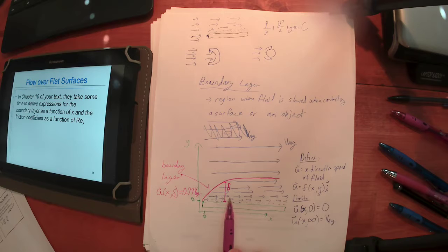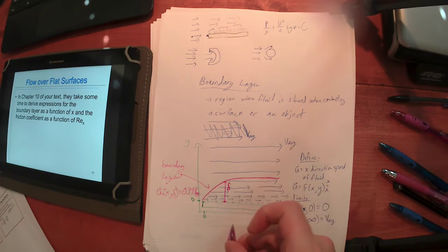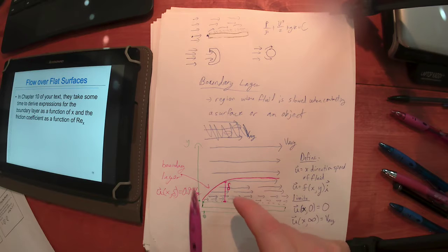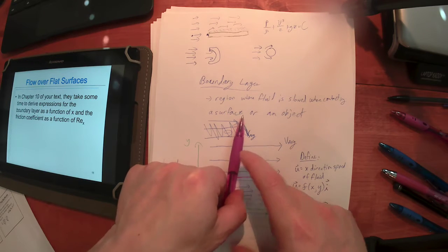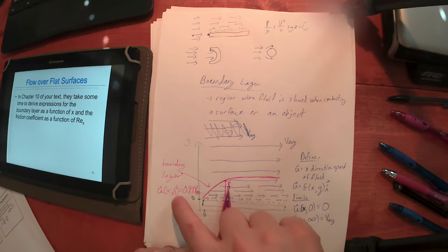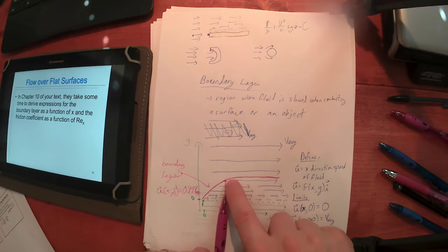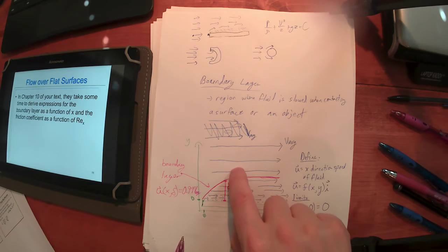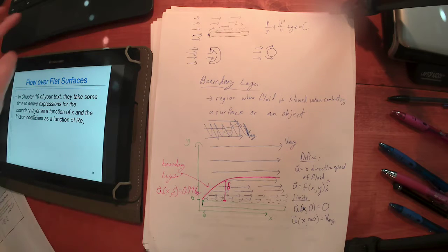And then they can move in a little bit further and measure the velocity there, and move in a little further and measure the velocity there. By measuring the length of the pin back here, they knew how far in they were, their Y value, and they could tell when they started detecting the boundary layer, when they kept getting the same speed measurement over and over again.